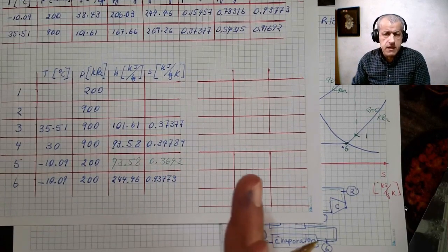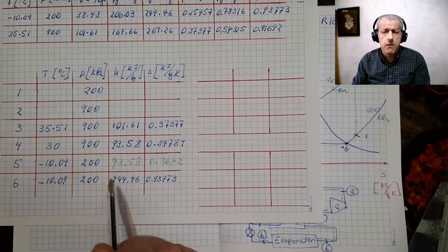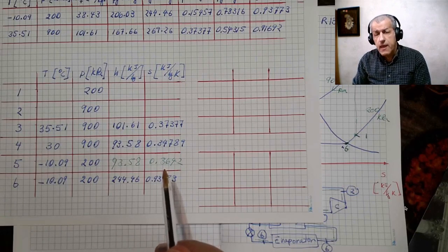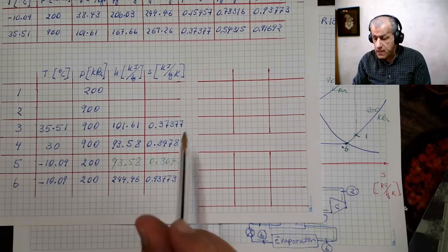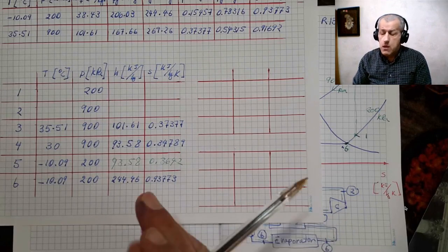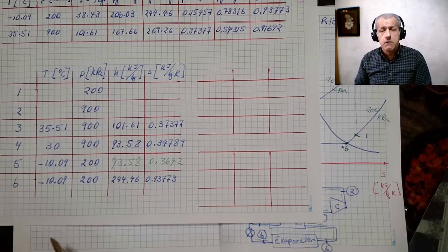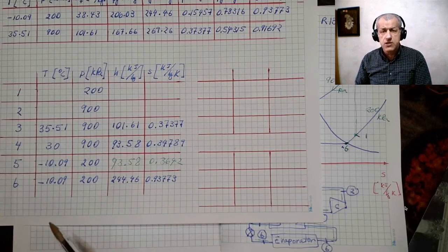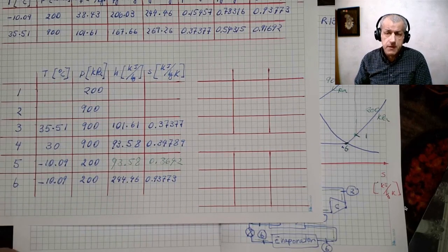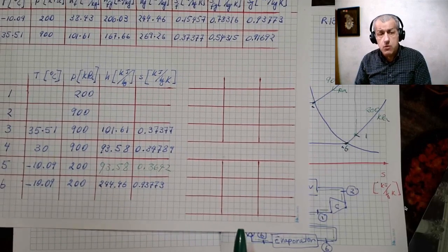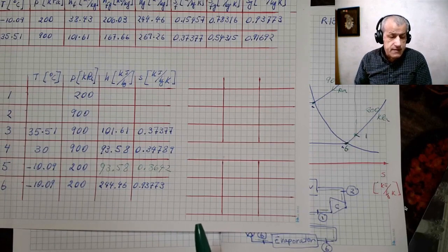We might need some of these values in this problem or not, but these are the basic values. Assume that if you want to do an exergy study on this problem, then you would need all the enthalpy and entropy for every point. So once you have calculated all these values, then it would be very easy to do all sorts of post calculations for all cycle properties or do an exergy study on individual components or the whole cycle.